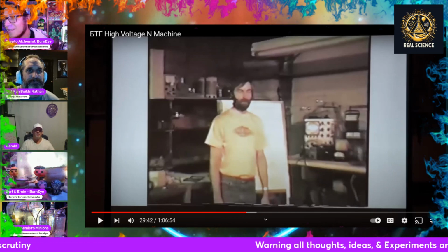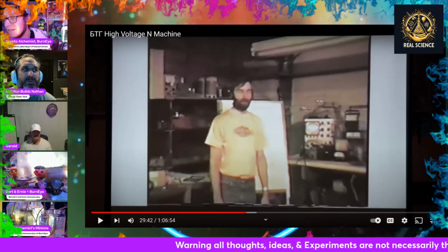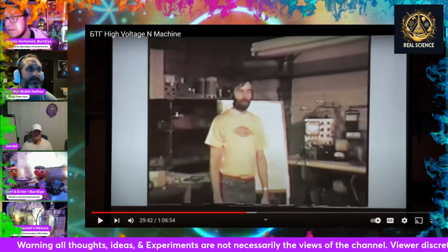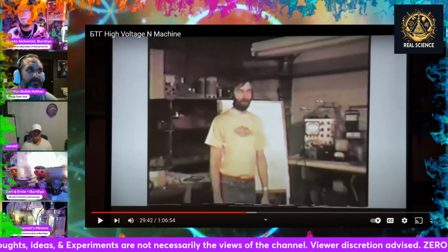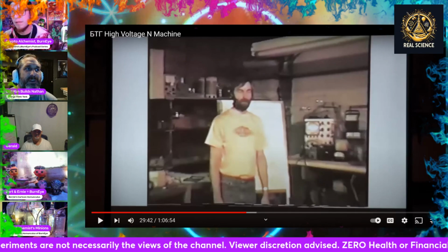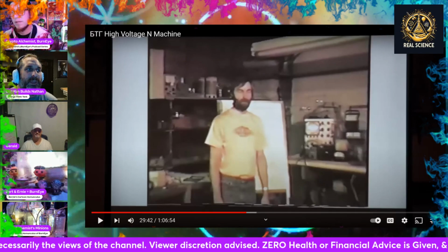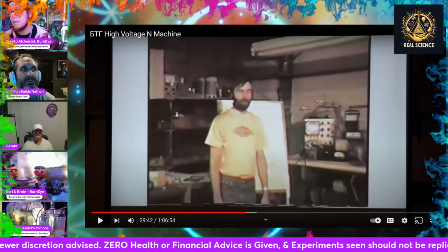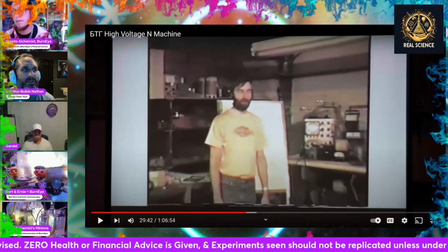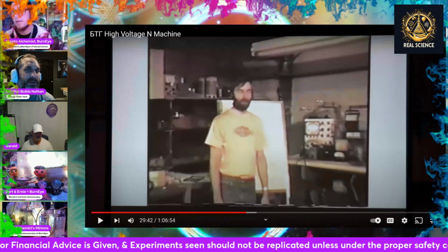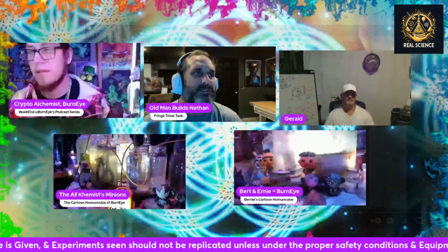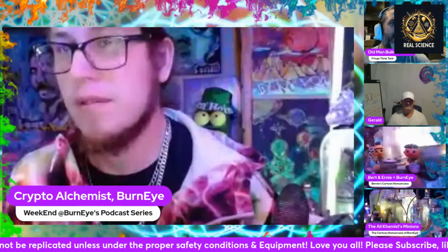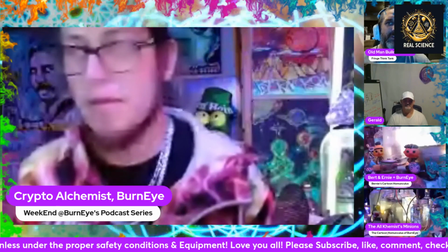But what were you going to say, Nathan? Did you guys understand why they changed the magnet configuration? They kind of glossed over it here, but in order to get an AC signal, it's got to go north-south, north-south. And when it goes over each pole, that's what's giving you your sine wave. So in changing it, they went from a solid magnet into individual magnets, and that's what gave them their AC signal out. Now, it doesn't produce as much energy, though.